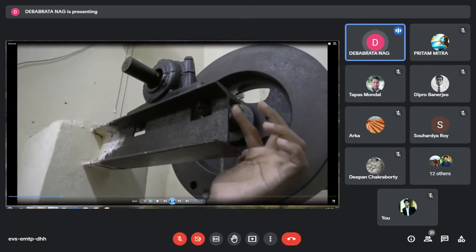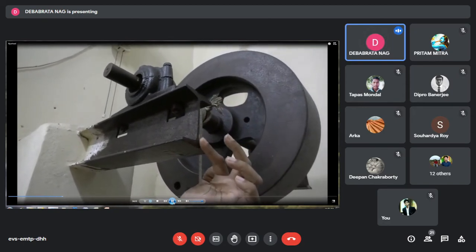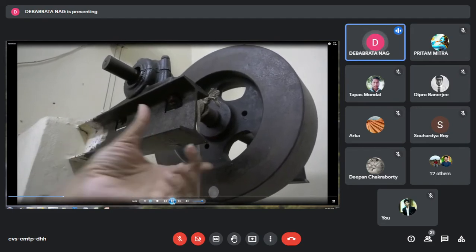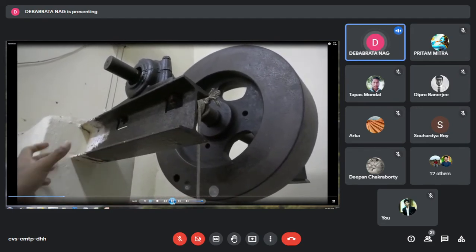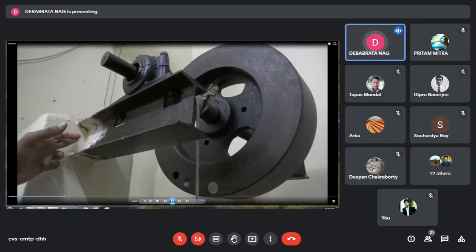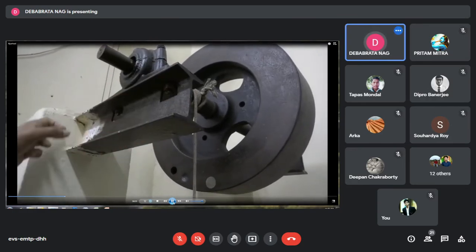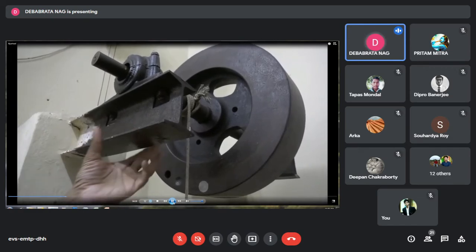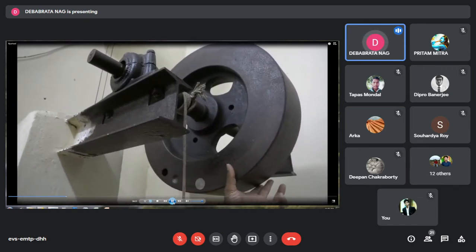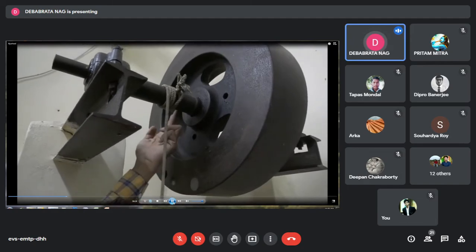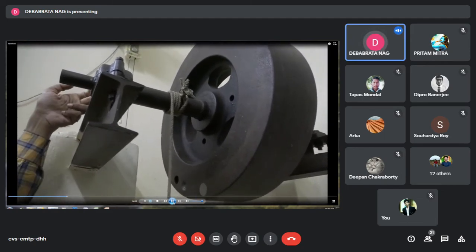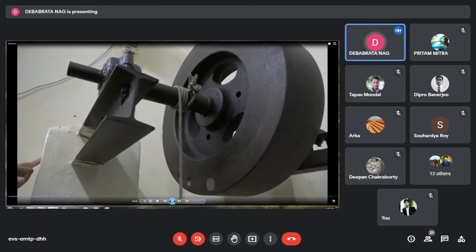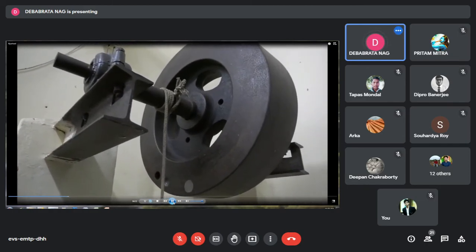In strength of materials, you must have studied I section beams. You solved so many problems. This is a picture of an I section beam. And if you look into its support, you will find it is a cantilever beam. This beam is fixed at this wall and free, with no other supports. So the weight of the flywheel comes through the shaft, through this bearing, through this Plummer block, to this cantilever beam, and then it is transferred to the wall.